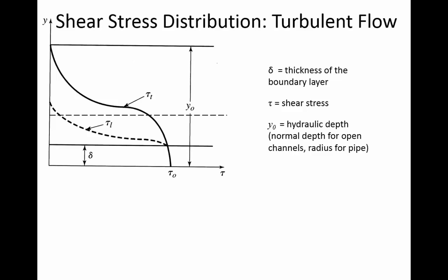And that's part of the reason why in a low velocity we don't have very much head loss. Remember that h sub f, energy loss due to pipe friction, is f L V squared divided by D 2g. So what this is a depiction of is saying if you have a low velocity, why is it that we don't have very much head loss due to pipe friction in low velocity? Well, it's because of the shear stress. The shear stress isn't reaching out into the fluid very deep, and the magnitude of it is lower than compared to velocity high.